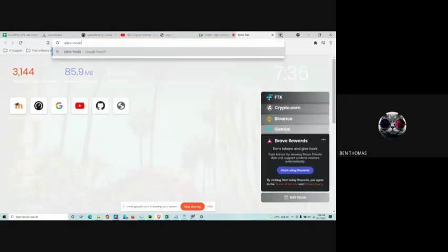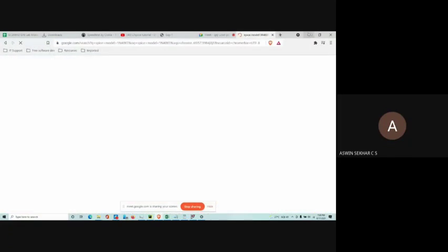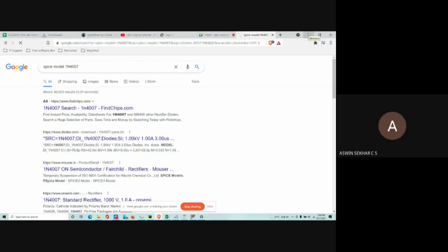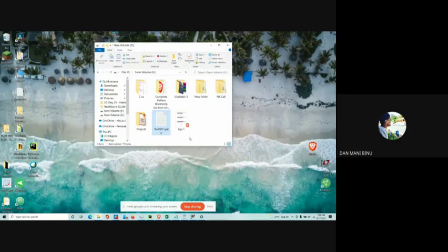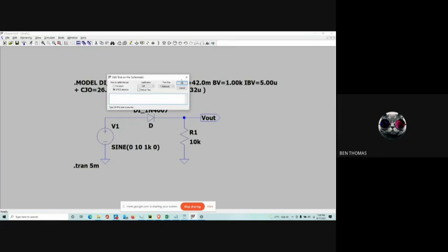Spice model. My doubt is, do we need to repeat the same procedure if we use this diode in future, or is it automatically uploaded in LTSpice? How can we permanently put the diode there? It's not inbuilt. For that you have to use another import procedure.